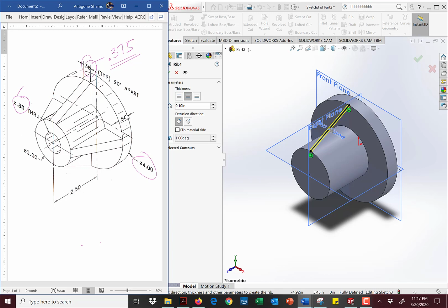This is out of your engineering graphics class if you're taking it with us. If you're not taking engineering graphics with us, meaning I teach at Triton College, if you don't take it there, and you're just learning this on your own on the internet, always pay attention to the fact that the number you see in front of you might not be the real number. Whenever you see an oddball number like this, 0.88, appreciate that it's probably 0.875.